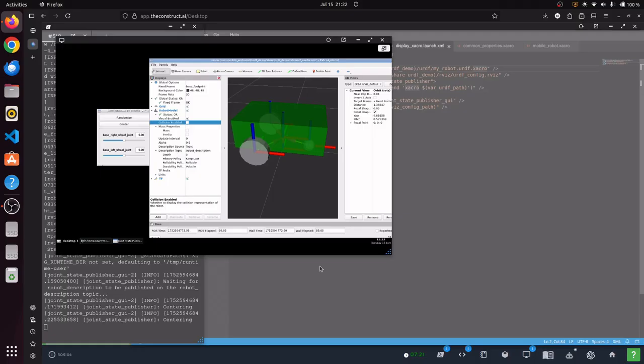Then you make the inertial model, and if you have defined Xacro macros, which I suggest doing in all your projects, in all your URDFs, it really reduces the time it takes. Then you call the Xacro macro or define the inertial tags and give it inertia, and then you make another link in the same way, and then you make a joint, and you just keep following these procedures to make other parts, and then your robot is ready.